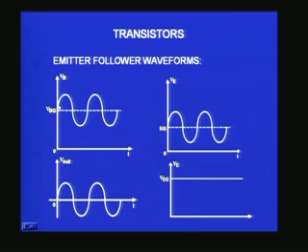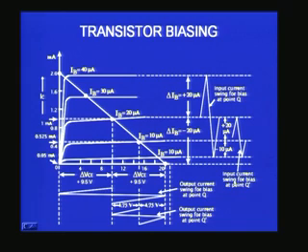I have drawn all the graphs here. With this is voltage VB at the Q point. You can see it is shifting slowly in a sinusoidal fashion. Similarly, the Vout also is sinusoidal. The difference is, even though they look alike, this is very small, this will be very large. And similarly here, the VE also will show this, but the biasing will not recognize this because it will be bypassed through the capacitor. But the VCC, the voltage, will always be constant because we are not changing that. That is from a regulated power supply.